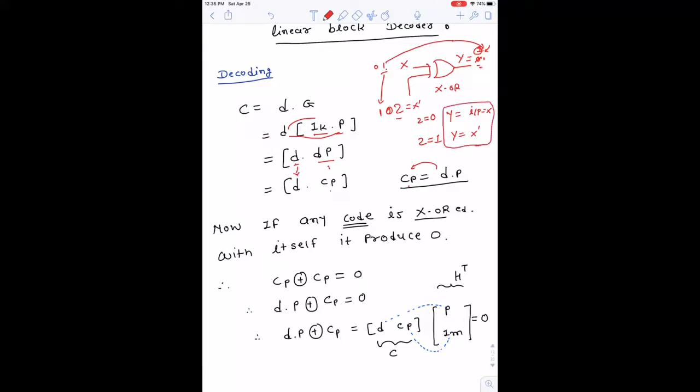This is a basic fundamental concept that you already learned in digital electronics, so I am not interested in going into detail about this. You take a look at this. If one input I keep as it is, and the second input I consider as a controllable input, and this controllable input Z I put as a 0, then your output is equivalent to the input. So this XOR gate works like a simple buffer. Whatever you feed at the input, the same you get at the output. But if I make my external or controllable input a 1, then your output is always an inversion of your input, X dash. So this part you have to learn so far.